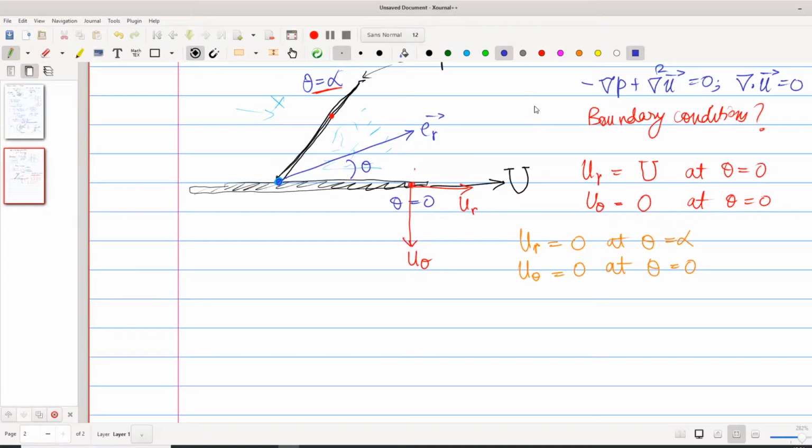So we can convert the governing equation into the form that we desire. Oh, that should be theta equals alpha. So now we must cast the boundary conditions in terms of psi and omega. First of all, let us see how we can write down the velocity. The velocity in terms of psi is nabla cross psi Ez.